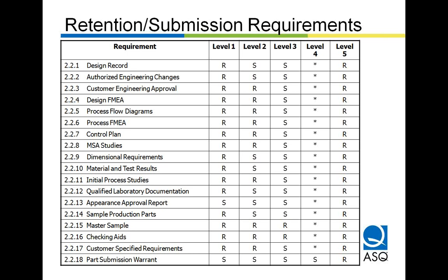When you have some type of a special cause going on that either you physically can't, or you, for financial reasons, choose not to address, then you should be using PPK instead of CPK to describe those processes. That's what's stated in the PPAP manual and the SPC manual. They're in concurrence on that.